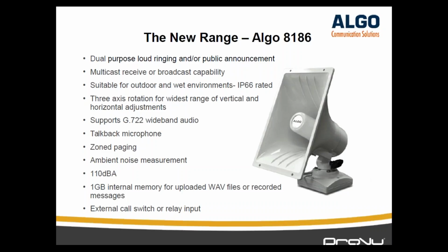This range supports G722 wideband audio. So when you make an announcement, it is crystal clear. G722 is a high definition audio codec, so the voice quality is highly improved. Most of the new PBXs use G722 for audio communications. But if you are installing tens or hundreds of these, or maybe 50s of these, you can just use multicast streaming.